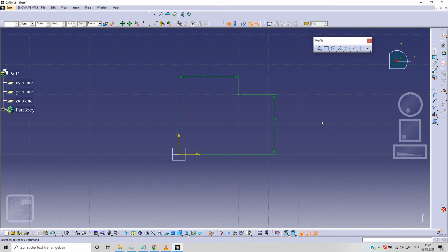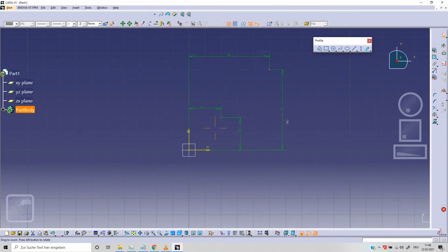We will work with isoconstraint sketch. This is the most important thing in Catia. We've got different options. We can use point by using coordinates. Clicking on this point, we need to introduce different coordinates, for example 50 and 15. Okay, and now we've got a green point, and this is an isoconstraint sketch.